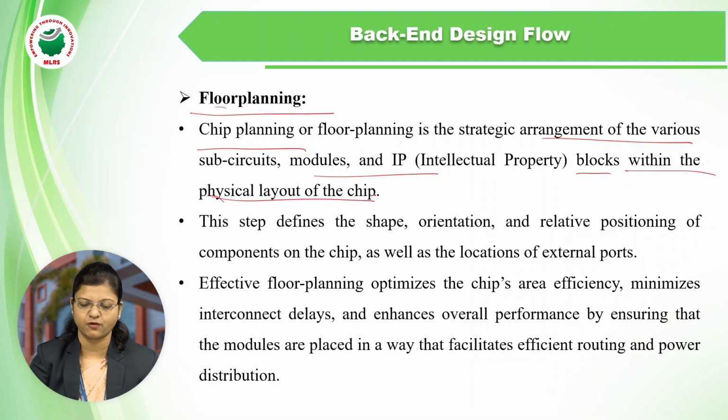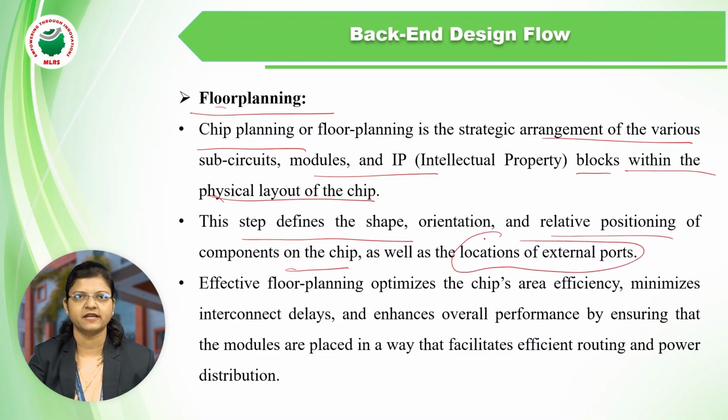So within the physical layout of the chip, we have to strategize and arrange all these sub blocks, modules and IP blocks. This step defines the shape of the complete design, the orientation and relative positioning of the components on the chip, as well as the location of the external ports. So what do we get after the floor planning?